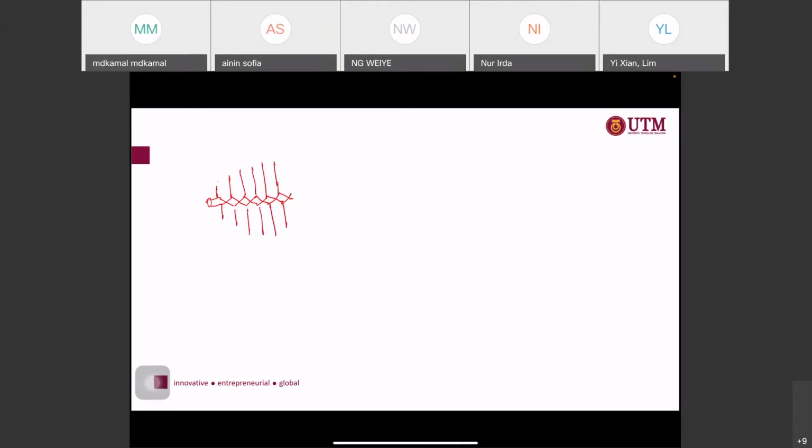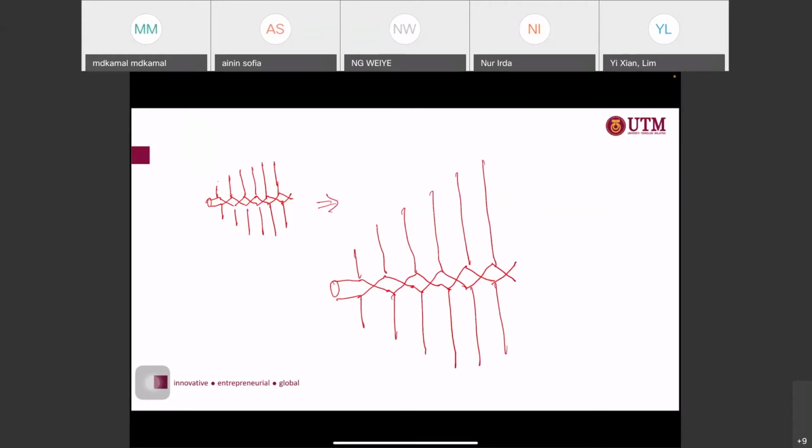Maybe we can make it a bit bigger so that you can have a better understanding. Let's say we move like this. I put it in terms of the crisscross here. Let's say this is your dipole. This is the dipole type of log periodic antenna. As you can see, this is the apex angle at the center. That means you excite the signal throughout this cable here. This is your coaxial cable, the transmission line.